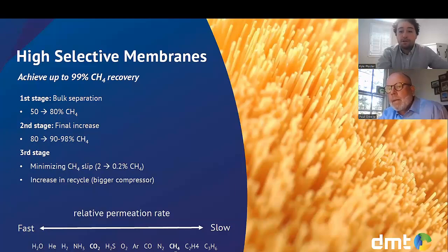So we really put the temperature really high, and the high temperature will allow more gas to permeate through the membrane. Usually we're trying to get all of that CO2, and maybe we'll get a little bit more methane than we would expect, but it's okay because it's going through that third stage and being recycled. So we'll do higher temperature in the first stage and then lower temperature on the second stage, so we're not losing more methane on that second stage that's not being recycled.